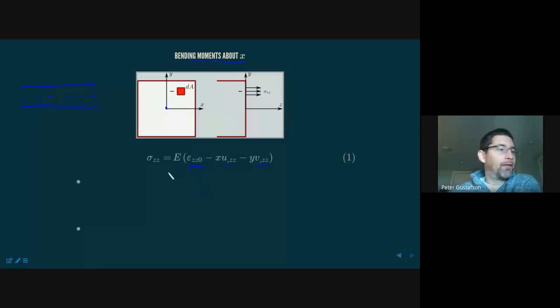Okay, I'm not hearing anybody volunteer, so I'll give another hint. Again, it's going to require an integral, and here I've defined dA, a differential area within the cross section, and we note a stress at that location. So I see Scott has volunteered in the chat window the integral of y times the stress with respect to the area. Very good. We're getting pretty close actually here.